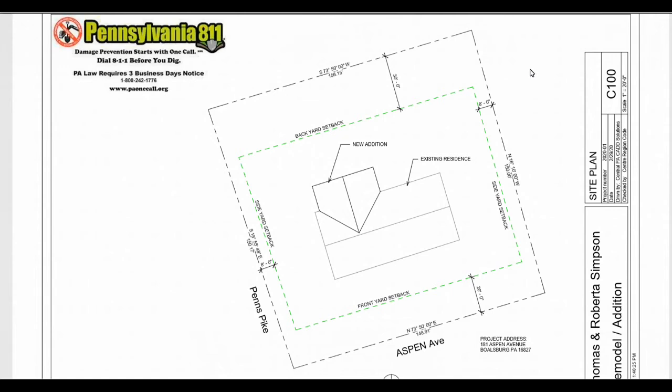A metal pipe, I've seen those. A lot of times they would use blazes in trees, basically take a machete and cut 3 little sections out of the tree so that you can see basically where the boundary corner is. So there's a lot of different things that are used. Most prevalently now are iron pins driven into the ground, and then there's a little orange plastic cap that goes over top of them. So you can find them easily if you start looking for them with a metal detector, and then you have to dig away a little bit of grass. You can see that orange cap.